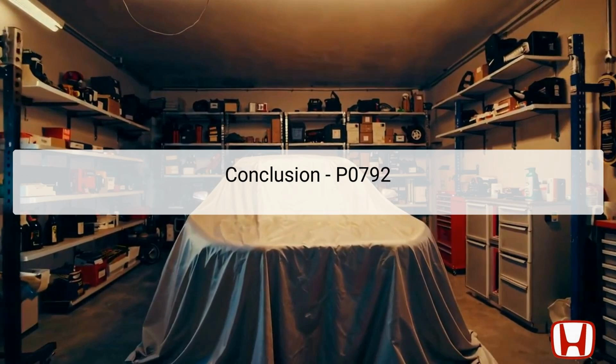Symptoms include the illumination of the MIL and the blinking of the shift indicator, surfacing during operational checks. Troubleshooting steps comprising engine start and monitoring through the HDS assist technicians in confirming the errors. Finally, careful attention to preventive maintenance can help in mitigating these issues in the future. By following this guide, Honda Civic owners and technicians can ensure their vehicles operate efficiently and reliably.